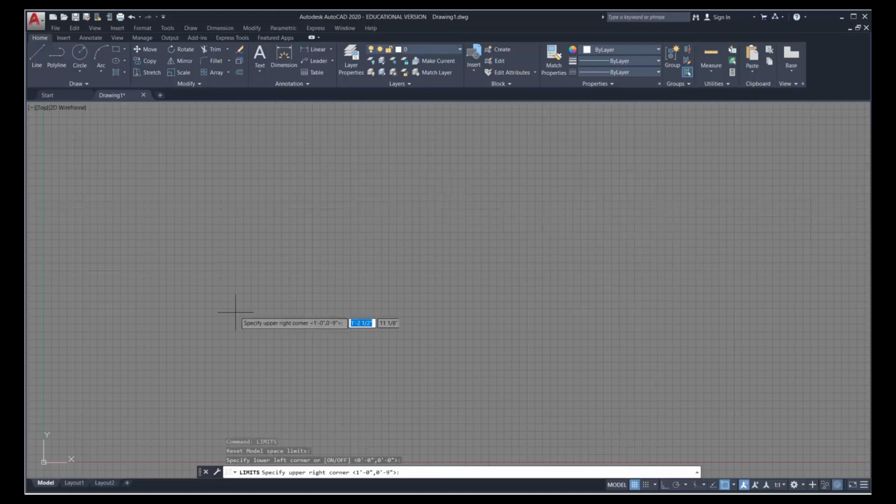Now it's asking me for my page size, and the page size is relative to the object. In this case, the object is very small, and we can fit it on a page that's 9 inches by 12 or 8.5 by 11. So what we're going to do is specify the width to be 12 and the height to be 9. Now, by chance, well, not really, AutoCAD DWT template automatically selects a page that's 12 inches by 9 inches, and that's why we've used these particular numbers. Now, you'll notice that the first value is 1 foot, the second value is 9 inches. So let's accept that and see what that means. Nothing happens on our page visually, but in fact, we've actually identified our drawing area. We just can't see it.